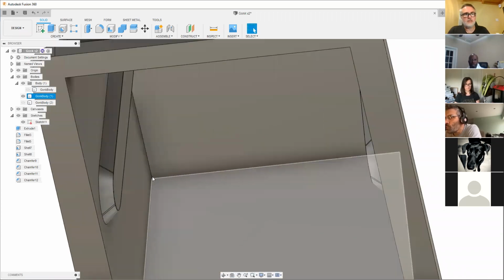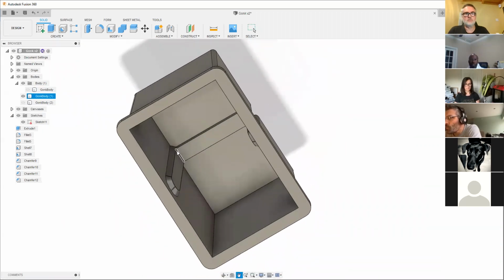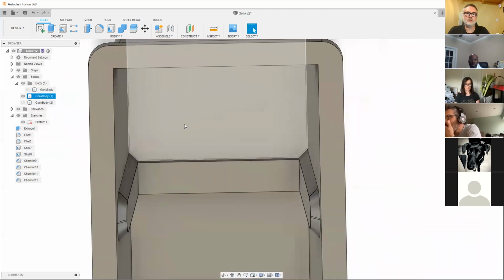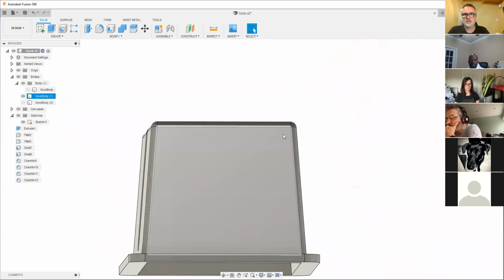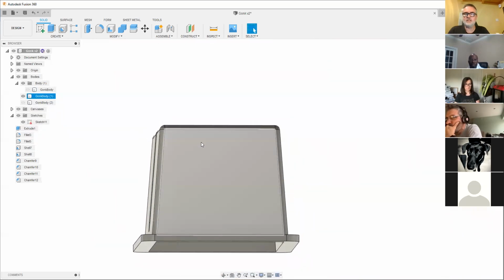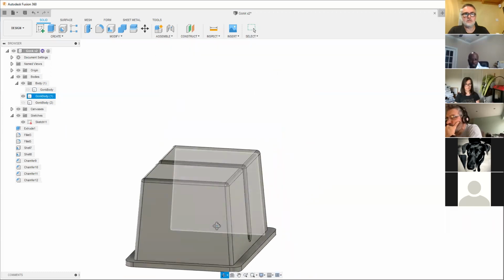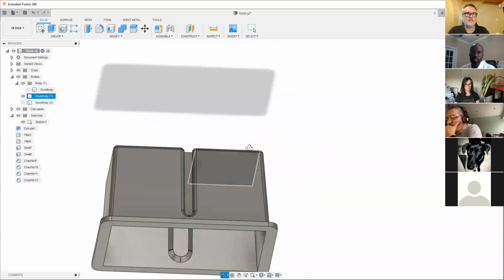The other thing to watch out for is if you put curved edges on the outside, when you shell it, it'll sometimes put curved edges on the inside. And curved edges bridging on the inside is not good, because your bridging has always got to be straight across, at a perfectly 0 degree angle to the print base. So again, it's just thinking about that as you go through.